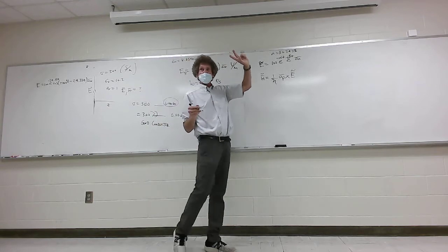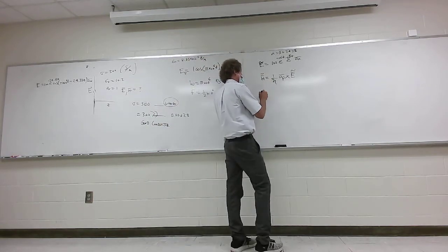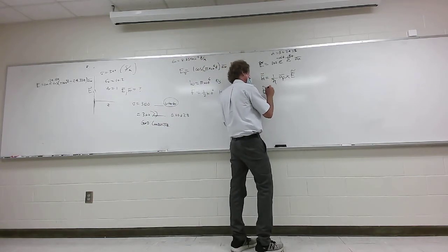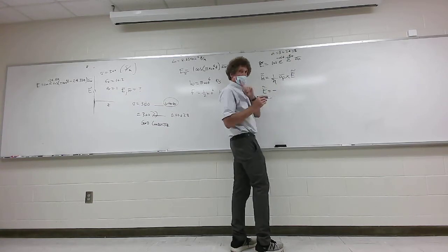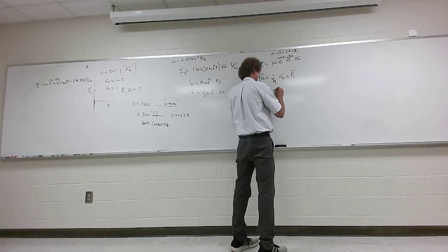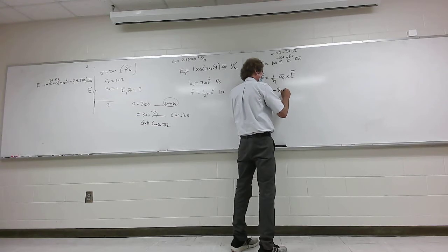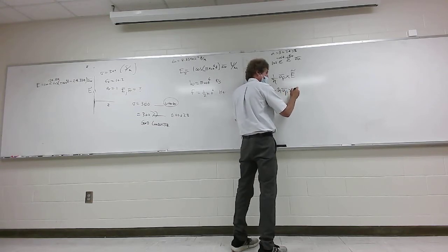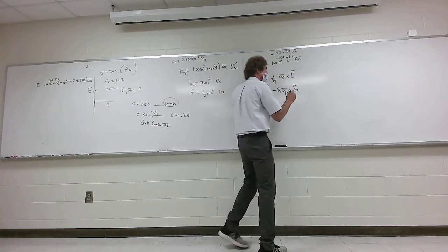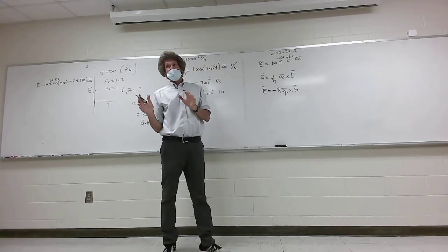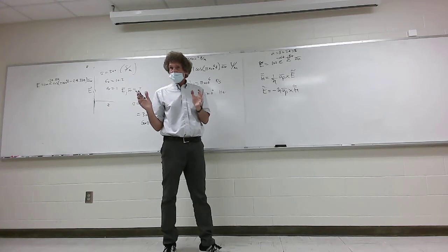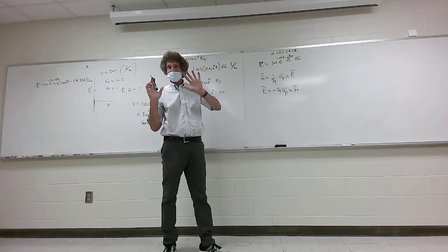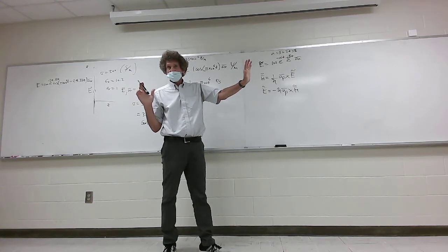Does anybody remember the other equation? What is E? Isn't it eta times the unit vector in the direction of propagation crossed into the H field, right, and this always works for plane waves. Remember that. It doesn't work in general for near fields, but it works for waves that are propagating a long way away from the source. Good on that, everyone?